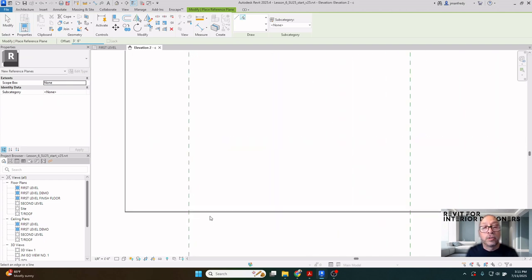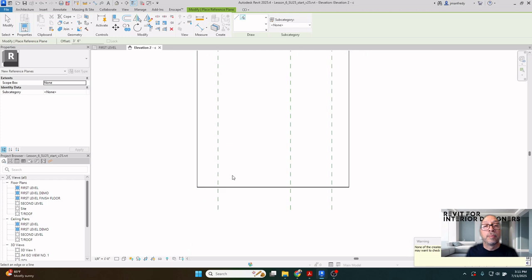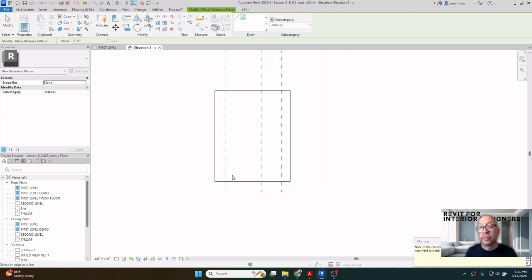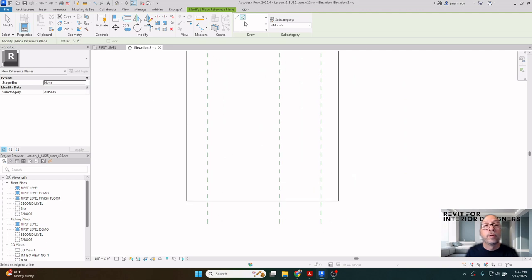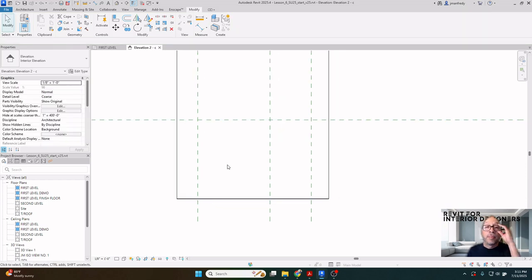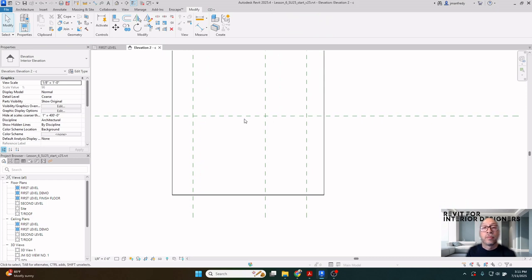So if I go down here and choose the bottom of the floor, it'll draw a copy, a line above it, 3'6" above. So if I use pick 3'6" and I hover here, you see the line is showing up there above. So I will pick that there. That's the top of the countertop. So this is 3'6", and it'll drop down to 3 feet.